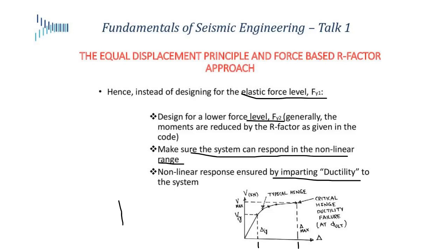Look, I have some bridge bent, and when I start to push on it, you see this first line is straight because it all stays elastic. Then something happens. Some part of it becomes plastic, just like I was drawing before. The hinge or the beam that we looked at became plastic. Now at that point, the structure becomes a bit weaker, so its stiffness then gradually reduces. So I form a second hinge, I form a third hinge. And by the way, a hinge is nothing but the point where the local cross-section reaches its moment capacity, okay?